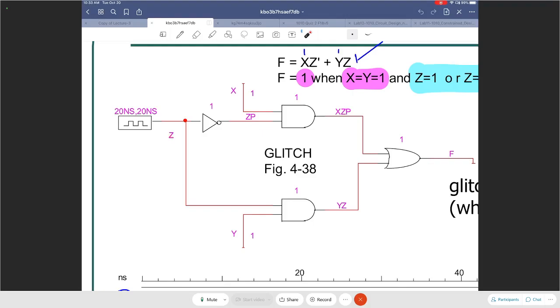From z to f, one path is through not and or, and it'll have one timing. And the other path is and or. It'll have a different timing because a not gate is absent over here. So this would count as a situation where there are two asymmetries all the way to the output with respect to the input z. Now, this still doesn't qualify the condition that there has to be three or more for a dynamic hazard to happen.